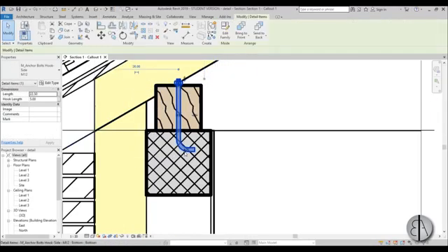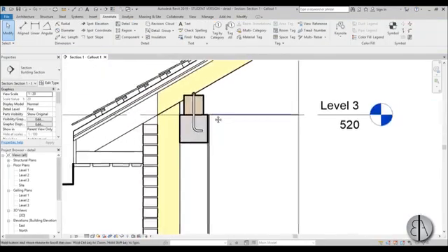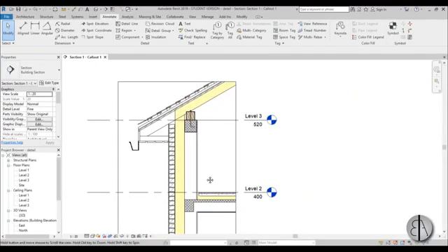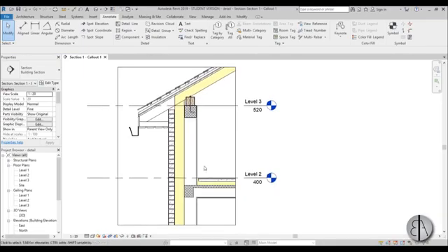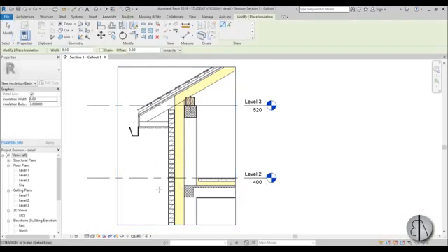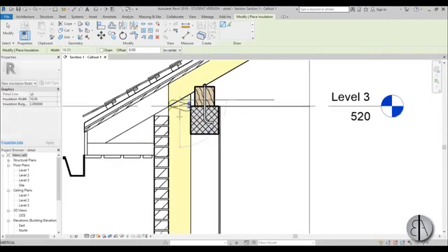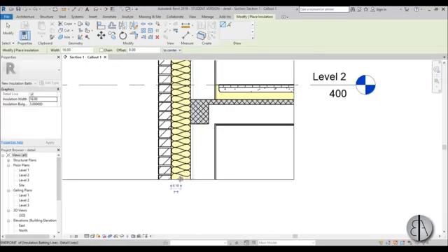Then you can select it and move it around a bit. So I think this looks about right. So we have our anchor point over here, and our detail is looking quite good right now. Now let's add some insulation. Just go here to Insulation on the Annotate tab to get this kind of wavy line. For the width, I'm going to type in 16 because I think 16 is right for this. If I start from here and go down here, yeah, that's 16.